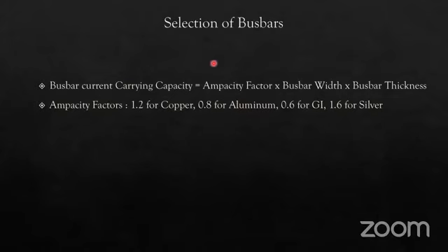The length of the bus bar is not much necessary in this case. You will only have to take care of the bus bar width and bus bar thickness here. Length can be negligible in terms of current carrying capacity.